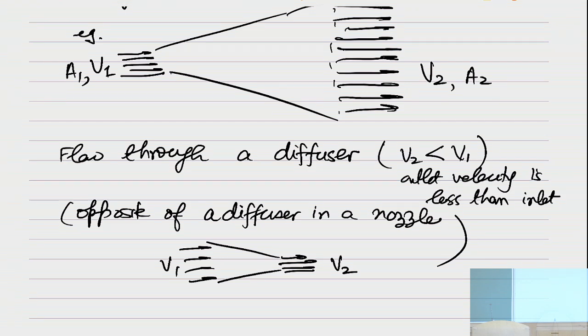And why does that happen? Because the density also changes in supersonic flows. So there the relation you have is not V1A1 equals V2A2. It will be rho VA equals constant. And the density will change so much that the velocity effect, if the Mach number is greater than 1, the diffuser becomes a nozzle, the conventional diffuser, and the nozzle becomes a diffuser.